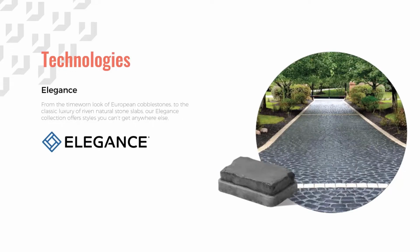Our Elegance line is made using wet cast concrete, whereas other products use a dry casting method. By wet casting the pavers, we are able to offer seamless textures and colors, as well as form finer features into the pavers. Additionally, our wet cast concrete unit pavers have a higher compressive strength to form an even longer lasting pavement.